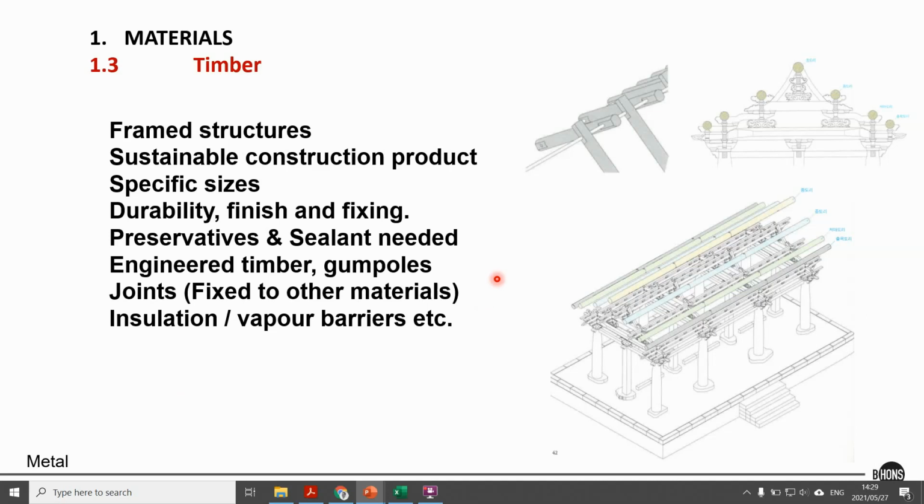Then we've got specific sizes, but you can actually move into what we call engineered timbers. Although before that, we actually talk about glulam beams or laminated timbers. So that's when you start gluing pieces together to make very deep beams. For instance, that's often used for beams. And the nice thing is, timber can be very homogeneous in its quality if you don't have to go for very long, big pieces, because wood obviously has heterogeneity in terms of its quality. But laminated beams therefore allow for that.